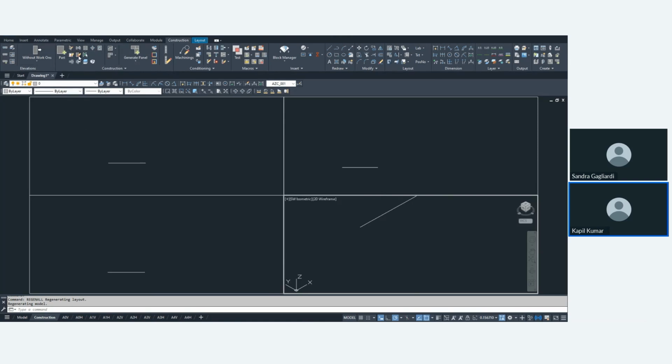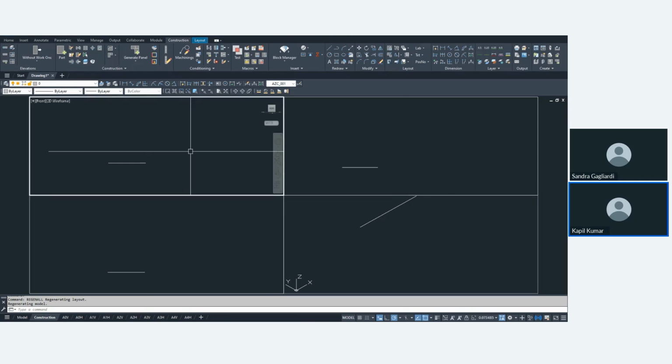Here we have 2 options for delete. The first option is out of the view, the second option is out of the drawing. Meaning, suppose you have multiple parts in front elevation and you want to work on only 2 parts, front and side. But due to wireframe mode, you are not able to find which is your exact part where you have to apply machining and so on. Then you can select out of the view for the parts which you don't want to see.